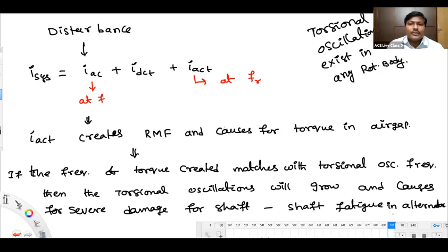Okay. So this is one of the major disadvantages of the series capacitor placement. Actually, we the people don't know about all these things. But one thing we know is that by adding the series capacitor, maximum power transfer capacity increases, fault level increases, and we have to modify the breaker. The people know only about these things. With those advantages, the people went for the installation of the series capacitor. After installing the series capacitor, after some time, the nearby alternator shaft was broken.